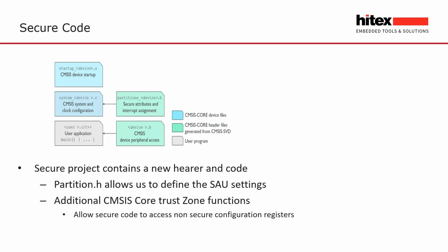Now, when we create our program, we can set it up exactly the same way as we discussed in week one. So in the runtime environment, we enable the device startup and the CMSIS support, and this will create us a minimal program that will get us up to main. So in our secure world, we can do exactly the same thing.